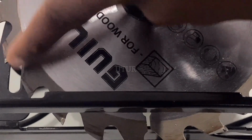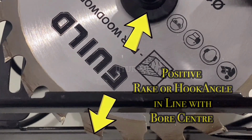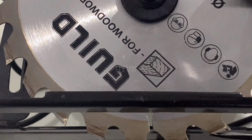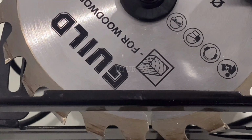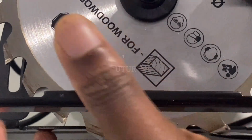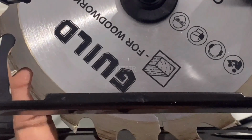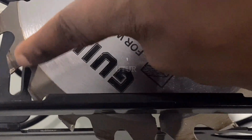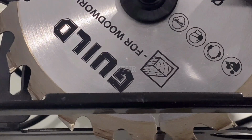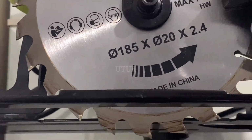So we can see that this ripping blade has a positive rake angle of anywhere between 0 to 20 degrees, and that's because you can see the inclination of the teeth. You can also use a flat top grind, an alternate top bevel, or a TCG configuration for rip blades. But for hard plywood, you will be better off getting a combination blade or a composite blade. And that's because the grain structure on your hard plywood is not uniform, it's haphazard.